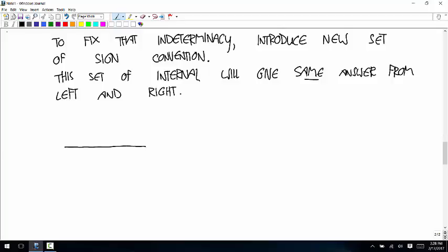If the part that you're isolating is the left, and you're calculating the loads applied to the left by the right, then the internal loads are going to be called the tension this way, the shear force this way, the bending moment this way, and the internal torque this way.